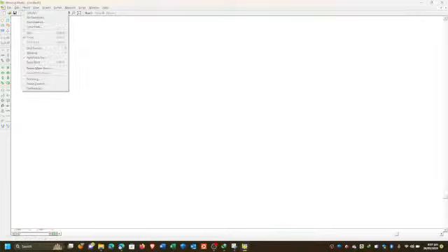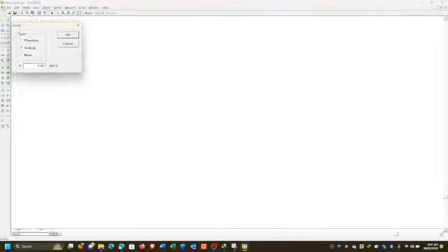You go to the World menu, for example, over here, Gravity. If I click Gravity, we have a mode here, vertical. If I choose vertical, I could now type in my own gravitational acceleration. If I say no gravity, it means the effect on the bodies on this workspace would be zero gravity.